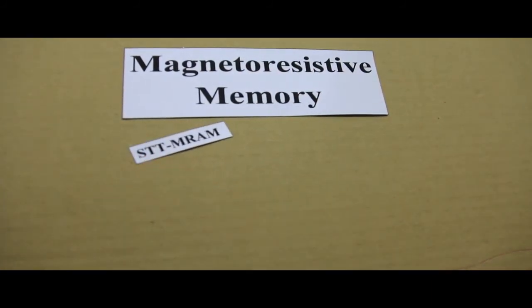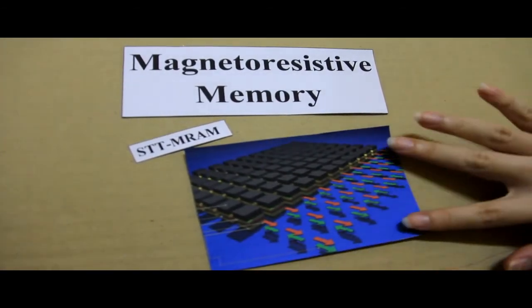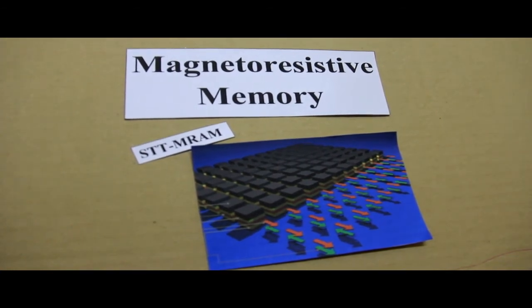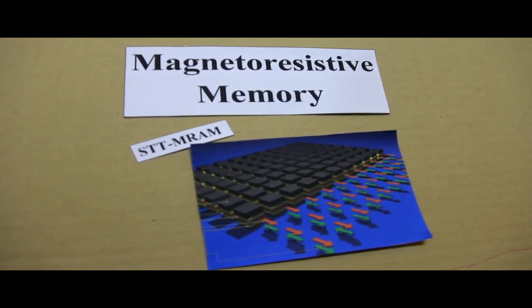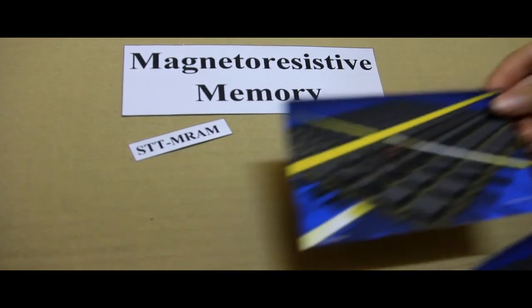The memories utilizing the latter effect are called STT MRAM. These types of memories are more attractive than memories using magnetic field for magnetization switching. It is because they do not require additional field conductors, and energy required to switch the single bit is lower.